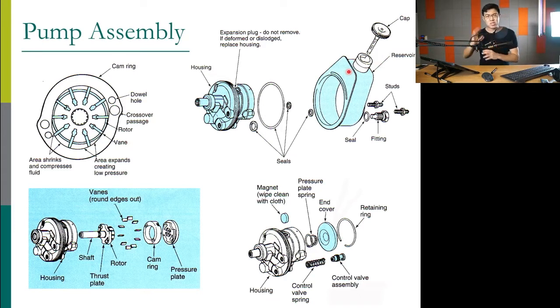So sometimes it creates too much flow, sometimes less flow. So we design it such that it creates enough flow at low RPM, because normally we want assist at low engine RPM. Now when engine RPM is increasing, the pump creates more flow. Therefore we cannot let that flow go out, otherwise it will create a lot of leaks at seals and many locations.